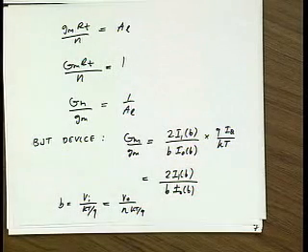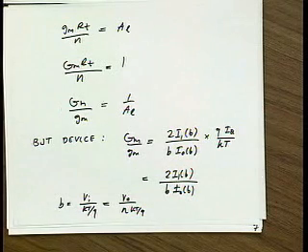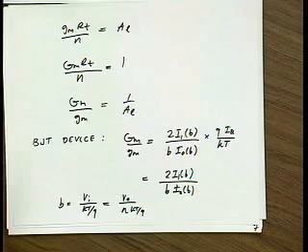For any other kind of oscillator, all you have to do is generate one curve, which is a large signal Gm versus the oscillation amplitude, and you have the recipe essentially for determining what the output amplitude is going to be. Okay? Question?